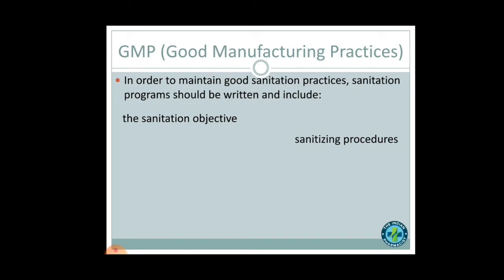For equipment surfaces, the most common substance used is isopropyl alcohol in 70% volume by volume strength. Sometimes thermal sanitization with a hot water system is also used.